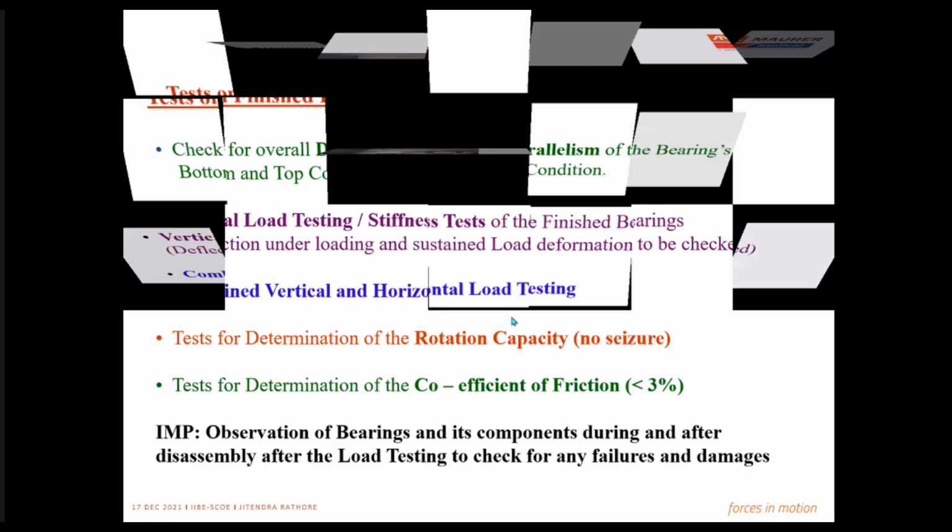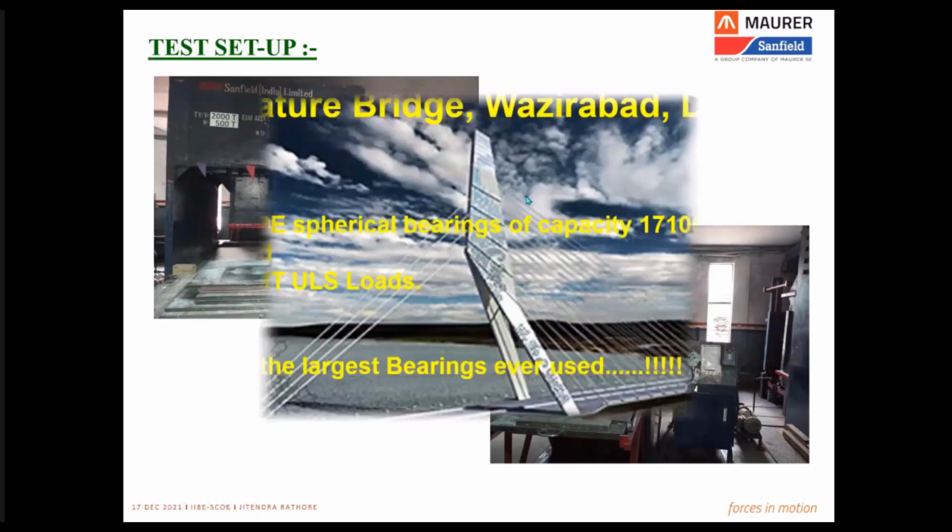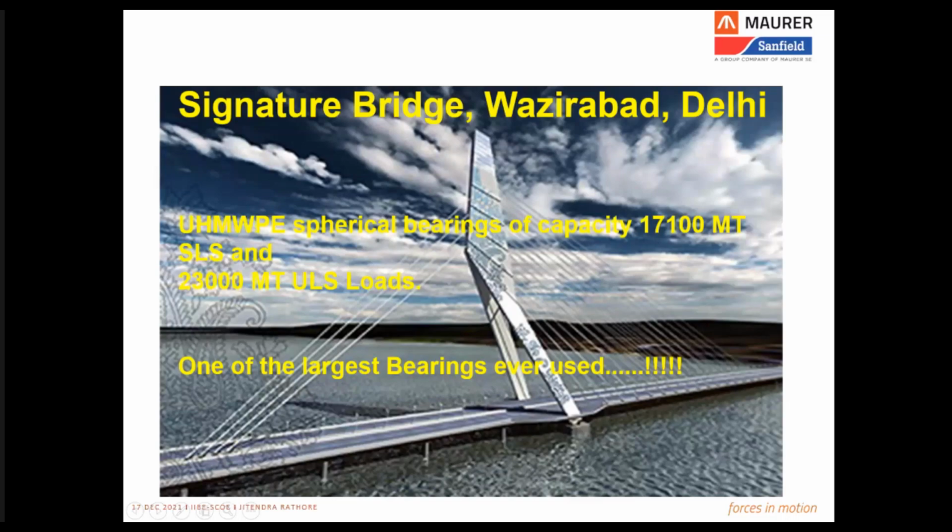Such reaction frames are used where the bearings are placed inside and applied with the design load, or maybe 110% or 120% of the design load. And after the testing, the bearing should not show any sign of damage or distress. So that was a brief about the manufacturing and quality control aspects.